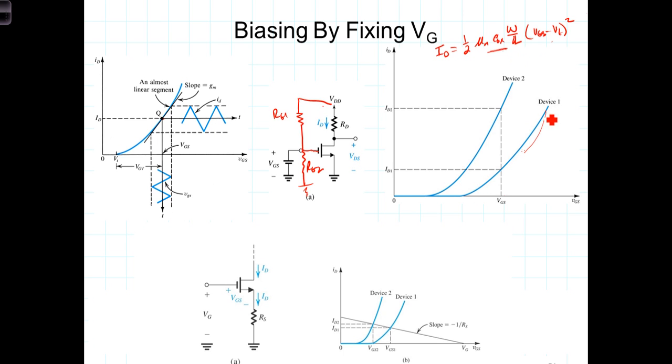And those two different devices may well have two different curves relating VGS to I sub D. So if VGS is stationary, having been established by the power supply and two resistors, VGS really isn't going to move very much. And for two different transistors, we see significantly different bias values for I sub D, and it places them into different relative positions on the curves themselves.